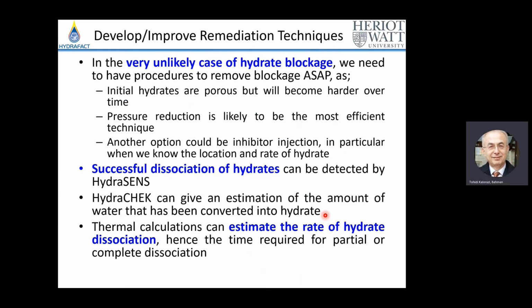In the very unlikely case of hydrate blockage, ideally you have to act very quickly. As I mentioned earlier on, the sooner you tackle hydrate, the better, because hydrate gets harder.